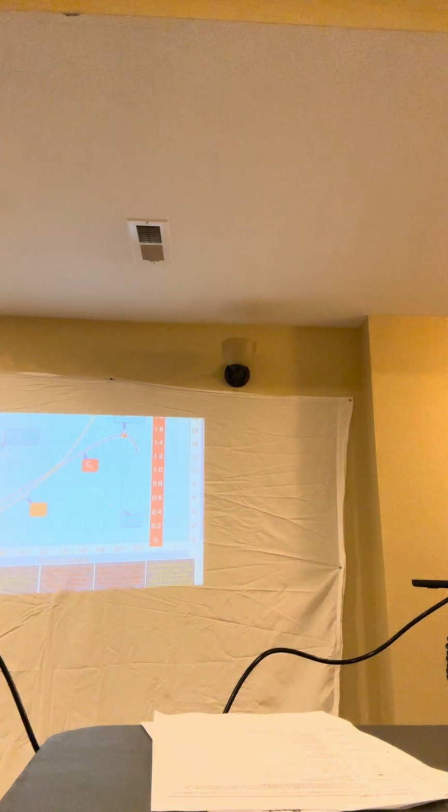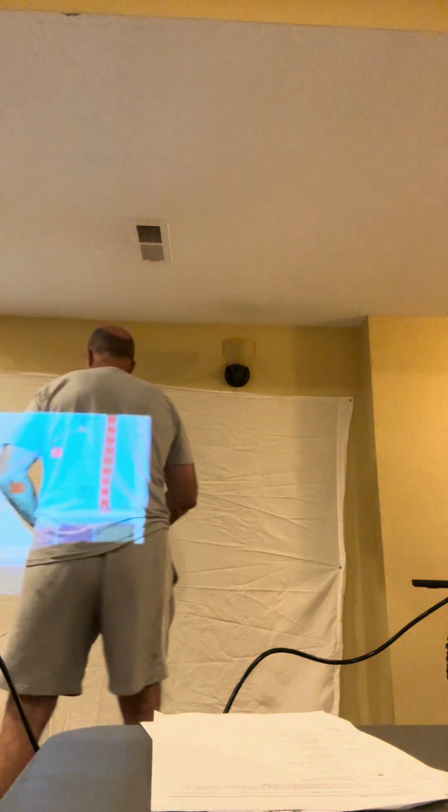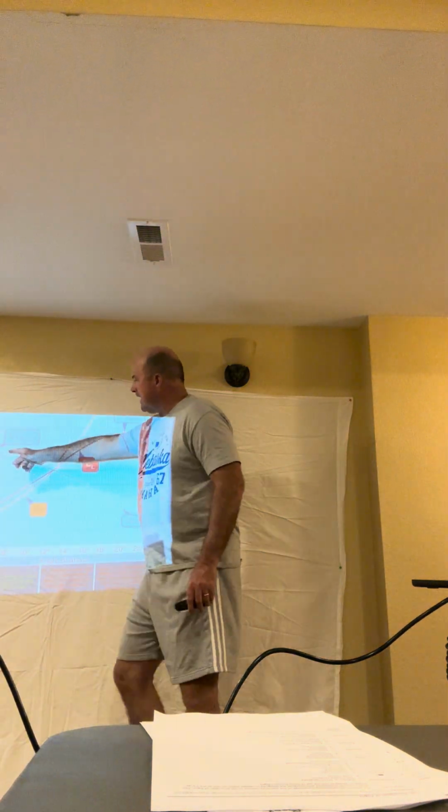It's the lift-drag ratio, right? It's generated by a wing relative to its drag. It gives you the airfoil efficiency, so how well is the lift? And the lift-drag max is at 6 degrees, right? Lift-drag max is right here at the top of the green arc.